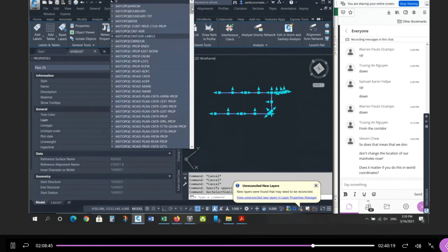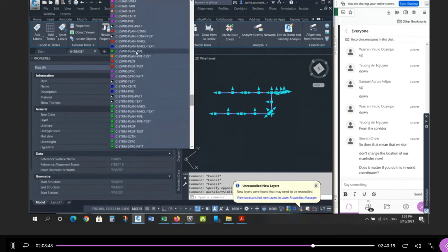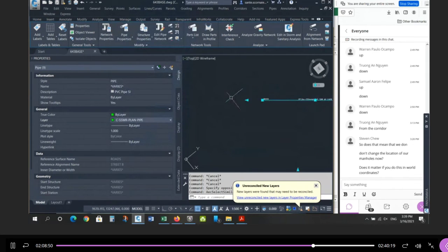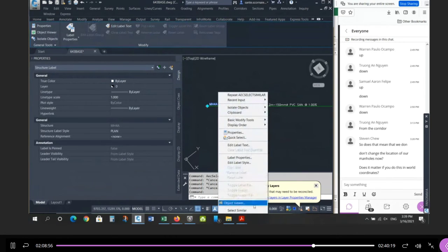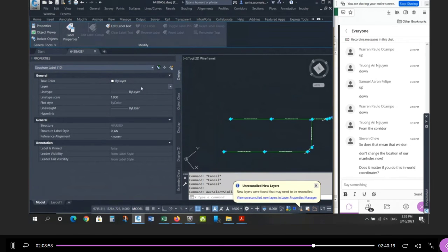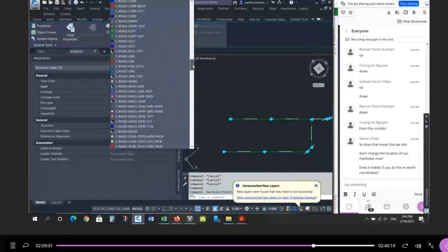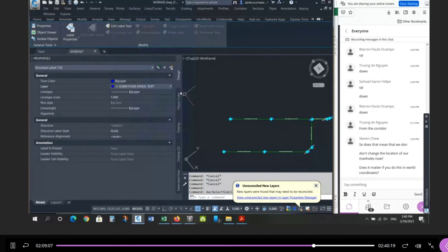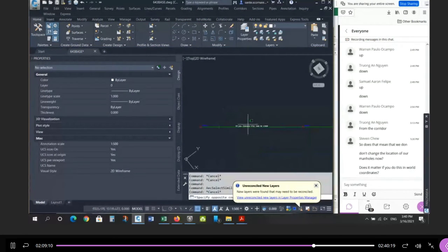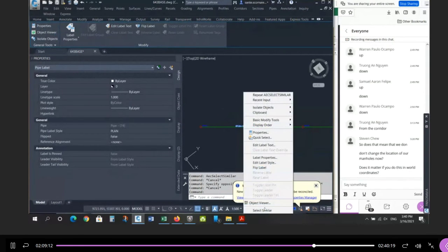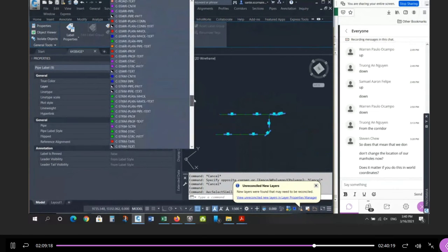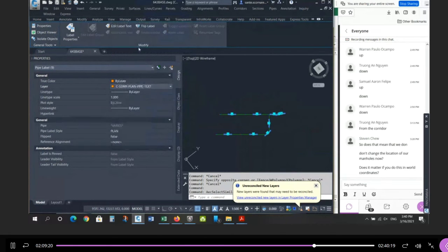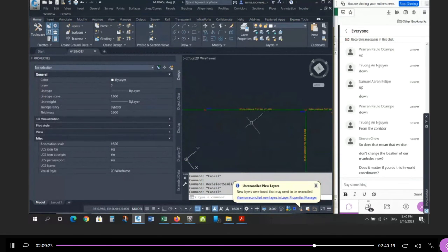Okay, so this should be on sanitary sewer plan pipe, so they should be orange. Oops, they should be green, sorry, the labels will be orange. So then this, select similar. These should be on a layer called sanitary sewer maintenance hole text. They'll come up blue, yeah, and then finally the label's going to come up orange. Select similar, so those are all the pipe labels, and change it to sanitary sewer pipe text. Right? So now you know that everything is on 4 layers.